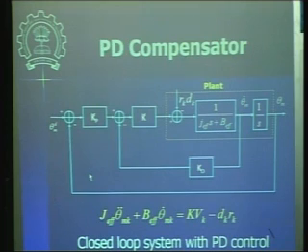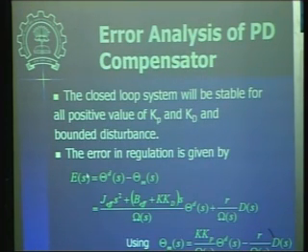Now let us do some analysis with whatever we have developed so far. If you use some theory about linear systems, the transfer function, basic fundamentals of automatic control, then you will find that this closed loop system, which is formed because of the combined motor and robot dynamics with PD control, is your system now.